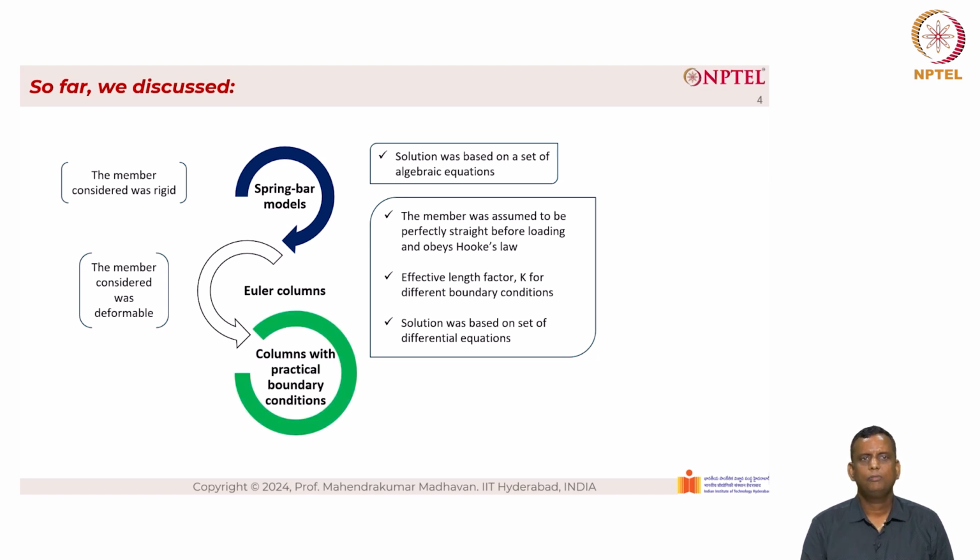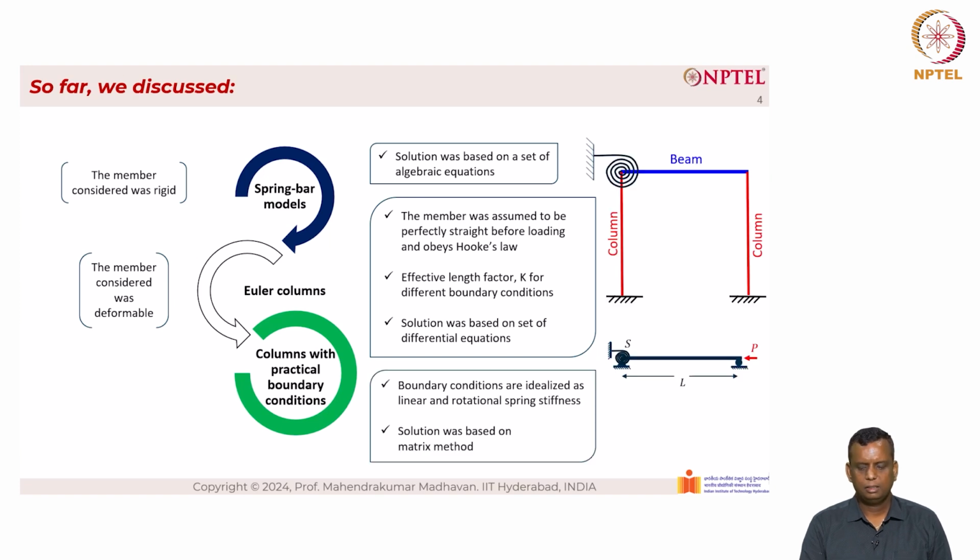From Euler column, we went to columns with practical boundary conditions. Here, the boundary conditions are idealized as linear and rotational spring stiffness, as you can see from the right side. The solution was based on matrix method.